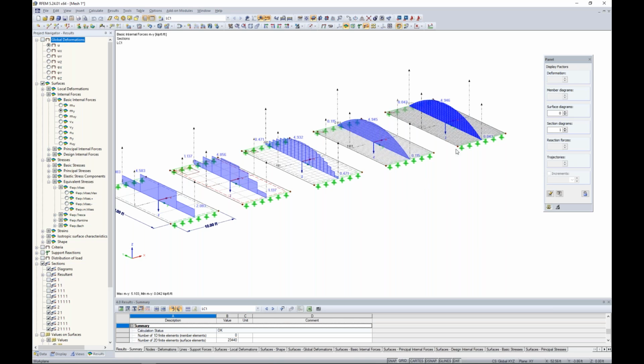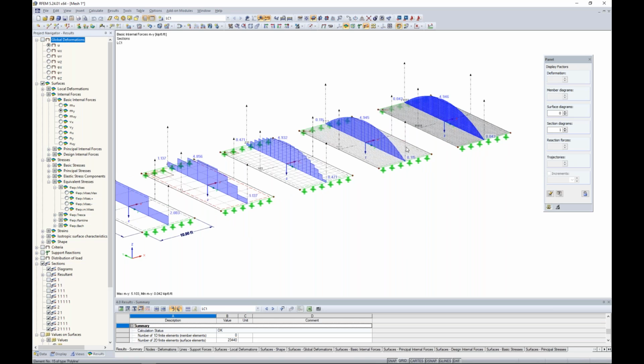So for example, these two elements here, the one on the left has about 1/3 the FE mesh that it does on the right, but yet our results are only changing by 0.001. So it's kind of this happy medium here to find out the right balance of when we are able to refine our FE mesh to gain accurate results, but not too much so that our calculation time is increasing significantly because we've added all these additional elements.